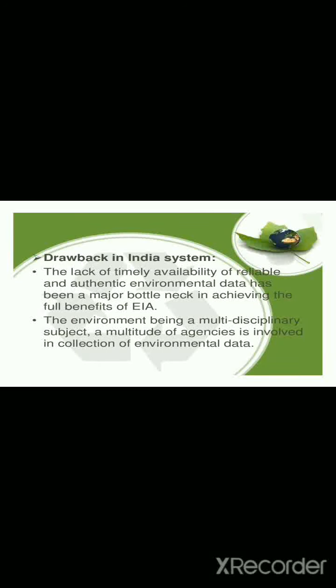What are the environmental issues of the project? Once the project is defined and all the alternatives thoroughly studied, this section presents the environmental issues around the final project. Each area of positive and negative impact must be defined in terms of its magnitude, reversibility, period of occurrence, and nature, that is primary and secondary.